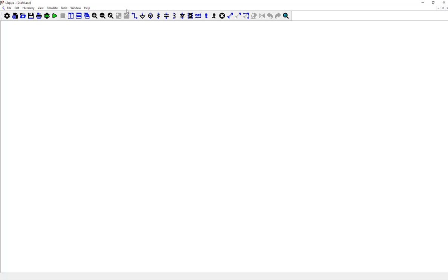In your PDF, I'm going to take points off if you don't follow. If you just copy and paste all these super dark background simulation files and all the curves are invisible, I wouldn't be able to give you the credit. Your super thin and light curves in the simulation on the black background won't be visible. Just letting you guys know. It's a really bad default simulation setting for LTspice.